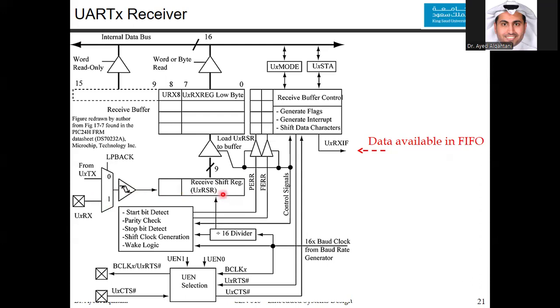And then here you store, while, let's say, you are receiving many frames, you also have a FIFO that stores 4 frames. So maybe the bus still needs to work on some values or doing some other job. You can store the frames here, 4 frames and 1 in the shift register, and you can push it into the data bus one by one when the CPU is ready.